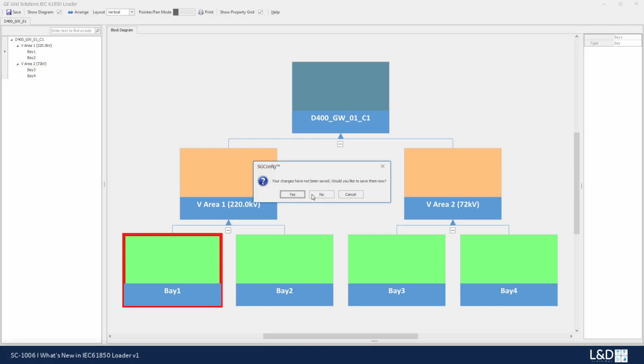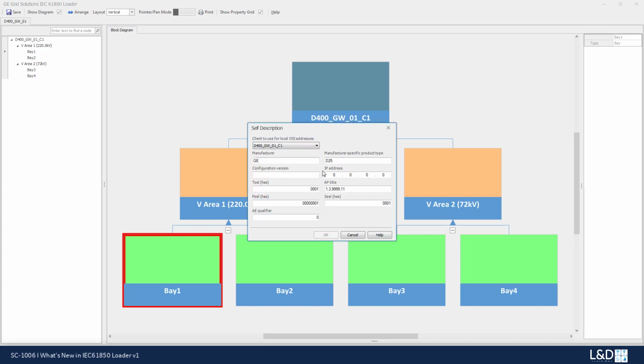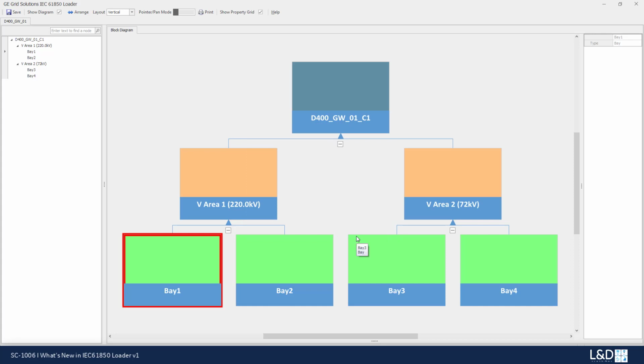So when we click OK here to open the file, we can save it. And so you could invoke the configuration of the IEC of the D25 and save it to the computer if the D25 is connected, just by putting the right IP address of the D25. I'm not going to show you this here, but it's an option that's available just by entering the D25 IP address.